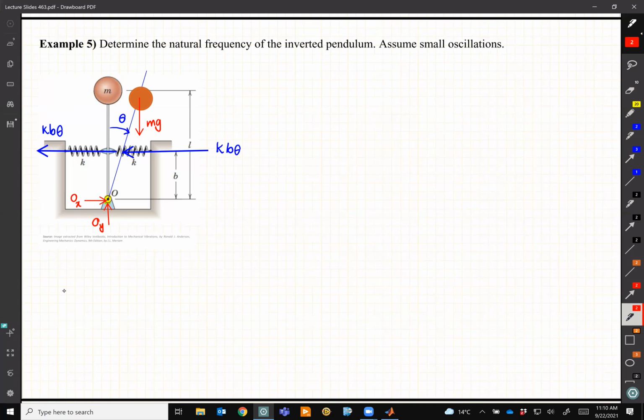So we have the free body diagram, then we simply use the Euler law. Euler law says if you have a rotating system, the sum of all the moments about that point must be I_O alpha. Alpha is the angular acceleration of this system. Something I said you need to be careful about when you take the moment. In statics or mechanics of materials, we had the convention that counterclockwise is positive, clockwise is negative, but here it is a little bit different.